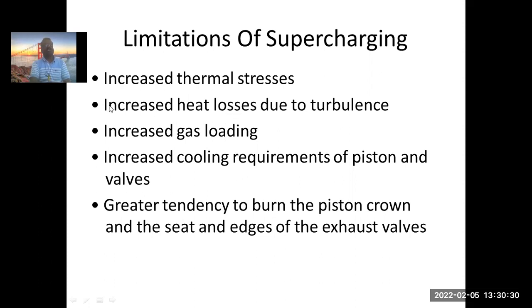That is a loss. And this particular heat loss increases when we implement supercharging in an engine. So that is where we say increased heat loss due to turbulence. Then increased gas loading, which means the pressure. When we talked about the thermal stresses, we also talked about the mechanical stresses. That is written over here in the simplified statements: increased gas loading, or in other words, increased mechanical stresses.